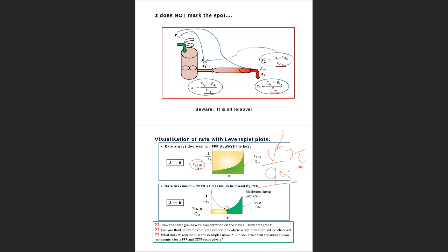Cool. Silence. If you've got no idea, just type no idea. It explains how long it would take to get the product. So yes, optimization, nope. Optimization I can do with volume, but thank you so much for answering. I can do it with volume. So I can say mass of catalyst, I can get less catalyst, and less is not always better because there's another price that you may need to pay in terms of the operating pressure or the operating temperature. It gives an idea of how long material takes to go through the reactor. That's all good. But why do you need to know that?